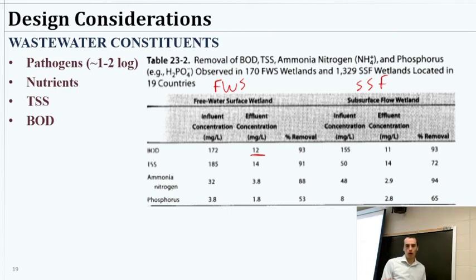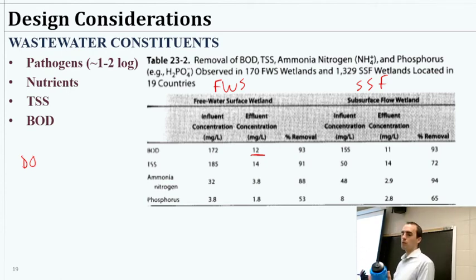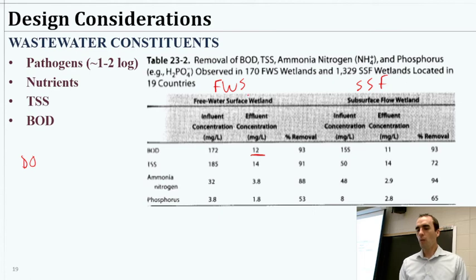Because our standard dissolved oxygen in my water bottle here is bound to be something like 8. It's not particularly cold, it's not particularly warm. It's probably somewhere between 8 and 10 milligrams per liter. So if something were to start removing that and was able to remove 12 milligrams in every liter, if I kept it sealed, this would go anoxic and would still have some BOD, or oxygen demand. Of course, hopefully there's not that much biological activity in there anyway, so hopefully I'm safe from that. But just giving you the conception here, what that means.